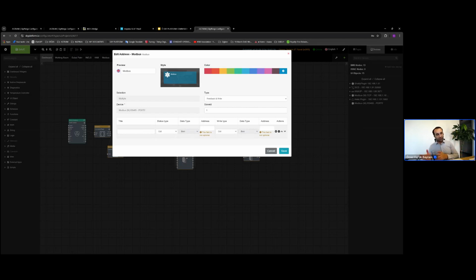That might be Modbus TCP as well. After giving this add-on or TCP connection, the Modbus gateway will provide us a register table, which shows in our unit what will be controlled with which addresses and which data type. These are data types. For example, coil: 1 bit, write and read. Discrete input: just read, 1 bit read. Holding register, for example, bigger size controls.